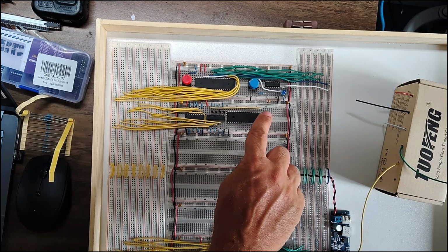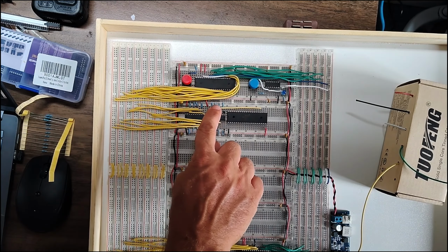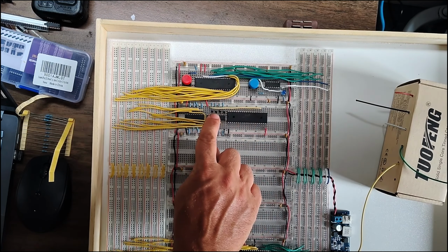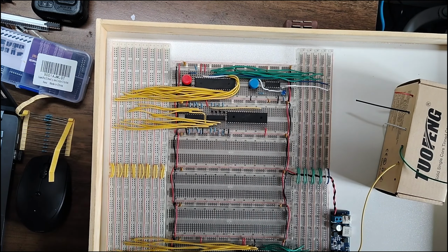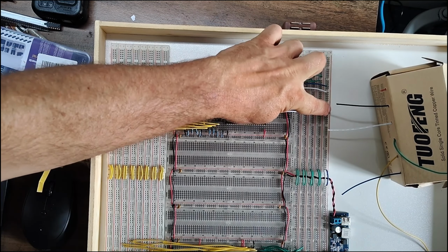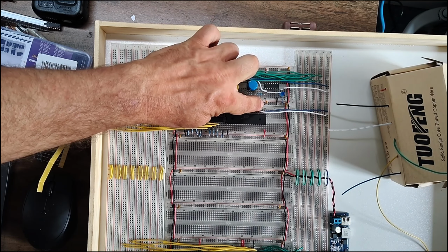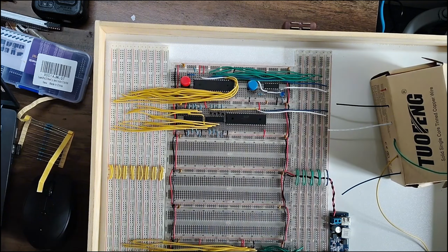Oh, and just one more, there is a chip select pin as well. So we've got one chip select pin here coming from the address logic. There's another one which has to be high in order for the chip to work, so we need to tie that high. So let's get those all put in. Okay, here we are. We've got the read-write pin connected. We've got the other chip select tied high. We've got the clock connected.